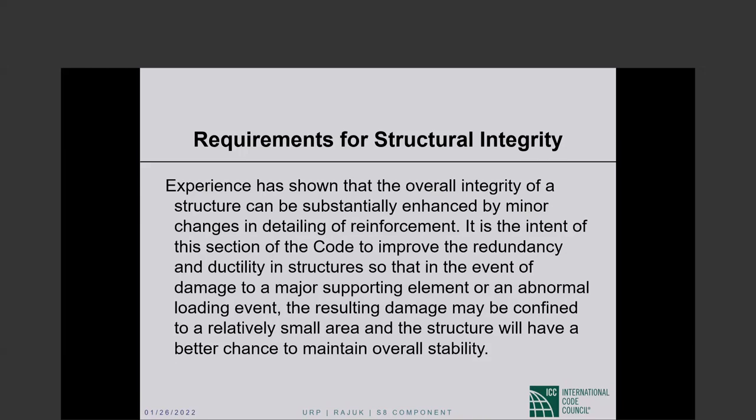But the dowels would have to be lapped with the upper bars and the lower column bars, right? So the lap splice length we talked about, even yesterday there was an example. You are lapping column bars, so you will have to provide a class A or a class B splice. Best of circumstances, it can be a compression lap splice. The dowel has to lap with the lower column bar and has to lap with the upper column bar. The lap lengths have to be sufficient according to the example that we went over yesterday, column bar splices. So that's what you will have to provide.